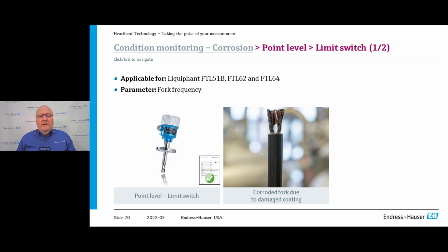It's constantly watching the frequency of those forks, and it has an embedded bandwidth that it looks at for either buildup or corrosion, due to a change in frequency. In corrosion, the frequency of those forks is going to increase because there's less material being vibrated. And we're monitoring that 24/7. So no matter what, you will get an alarm once it reaches a certain point. That's great, okay?